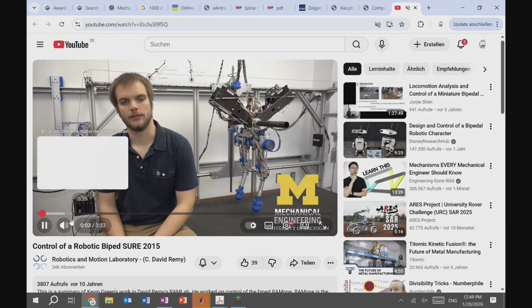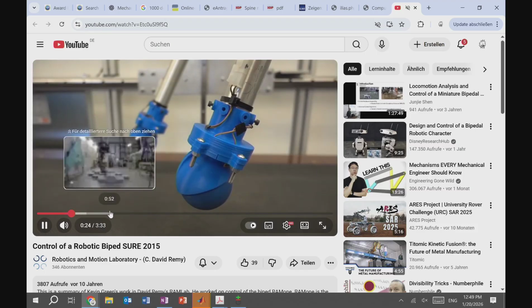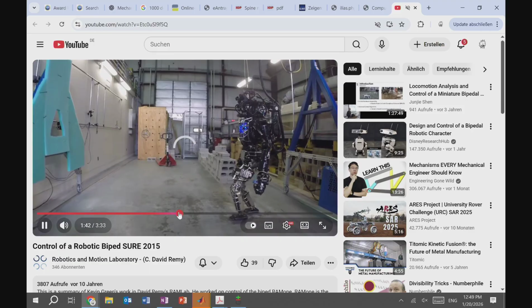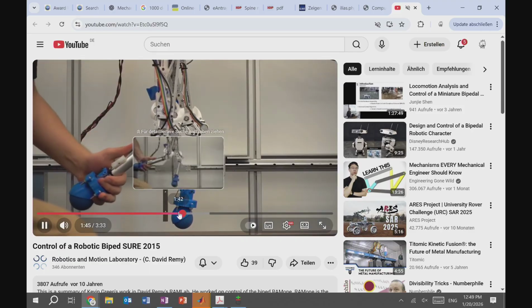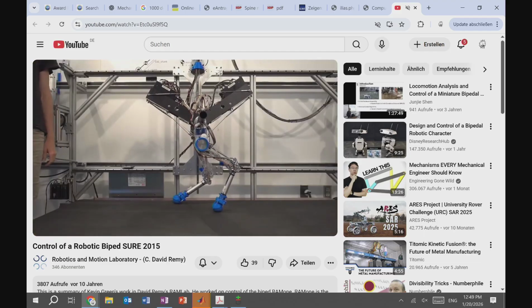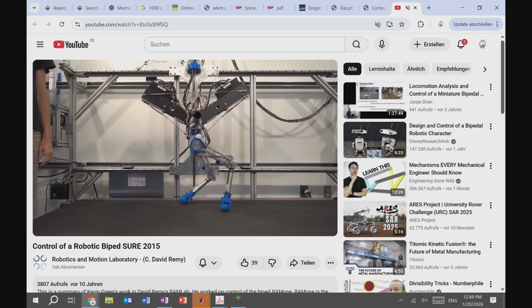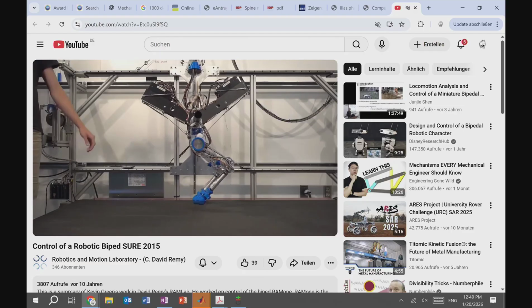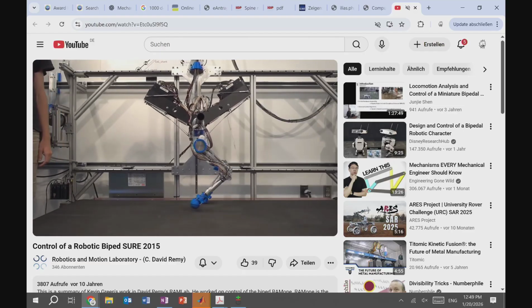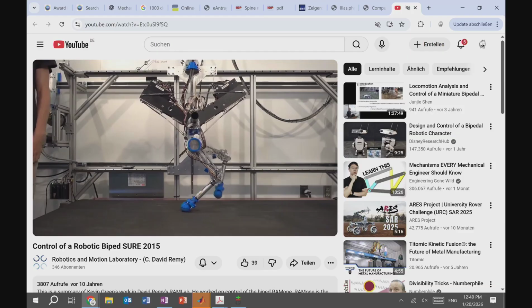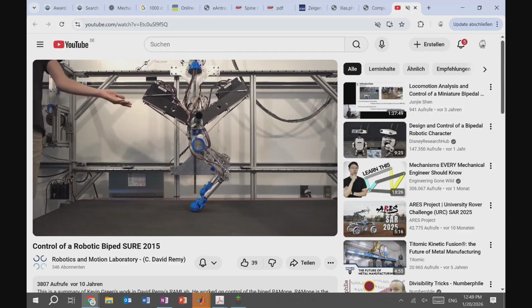So it's one of my undergraduate students who implemented this controller for the robot that we have in the lab. And the nice thing is it doesn't really matter where your feet are on the ground. We haven't even reasoned about where the foot is on the ground. Is it even on the ground? Is it in the air? Because, of course, that information somehow goes into these Jacobians. If I lift the foot up, the Jacobians will change, the lever arms will change, the motor torques will change.